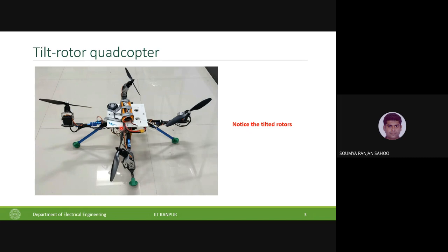The camera can be fixed to the quad frame because you can achieve zero roll and zero pitch while still in motion. With this, you can have a direct vertical view without any change in the orientation of the camera, and that reduces computational processing. If you have a camera which has tilted while recording something, then you do video processing to counter that tilt, and then you process this processed video. But in this case, you don't have to do this pre-processing where you remove the tilt, because there is no tilt involved.